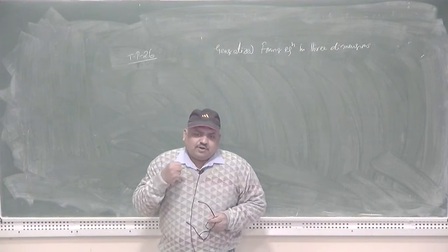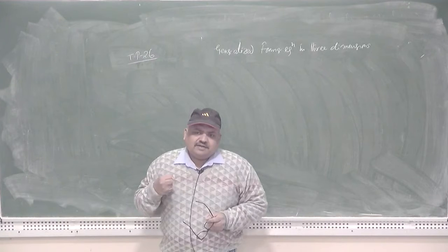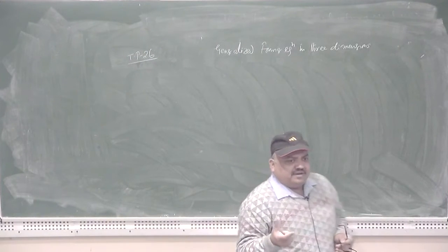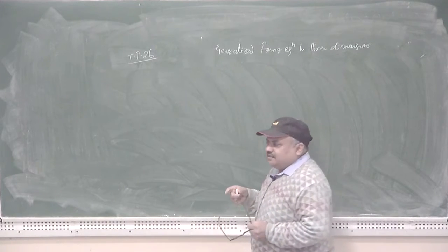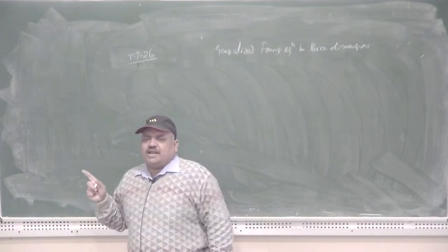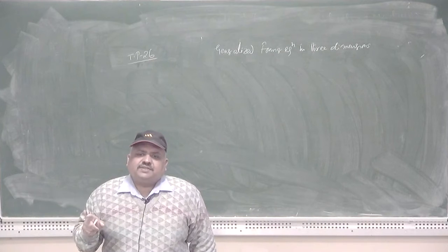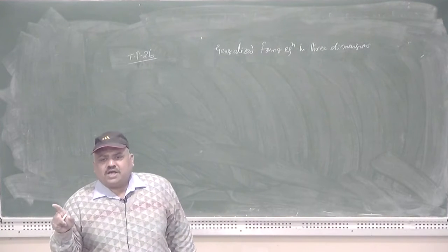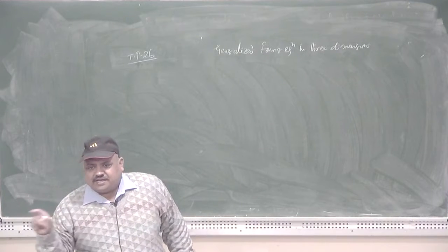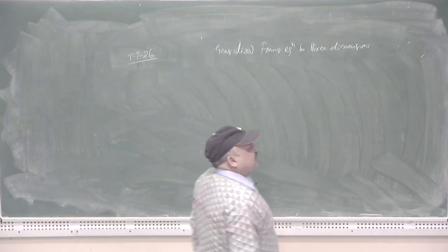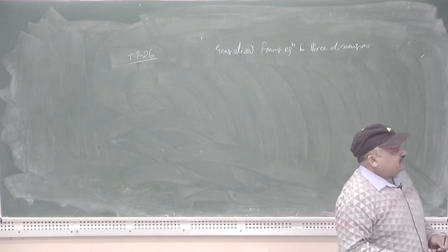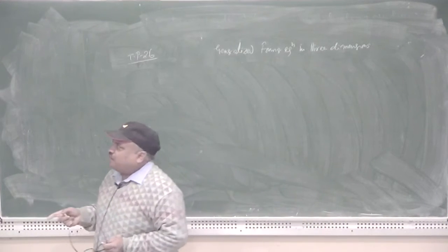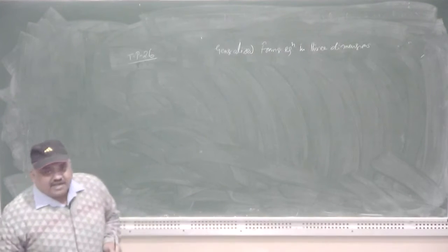Then you have to emphasize that in order to convert this 3-dimensional problem into a single dimension, you have to consider that the heat transfer rate along the other 2 directions is of such a magnitude that it may be neglected due to the infinite dimensions along those directions. That means, if I am talking about the x direction, let us suppose the dimension along the y and z directions is so infinite that heat transfer along the y and z axes may be neglected.